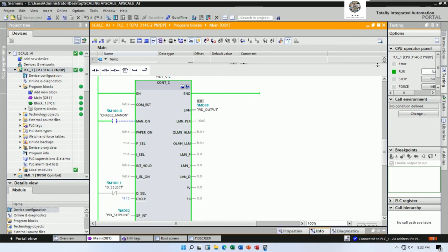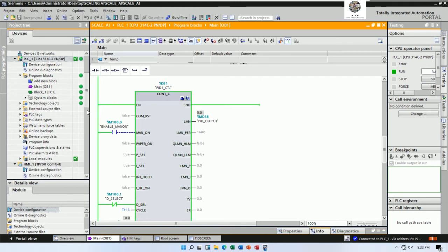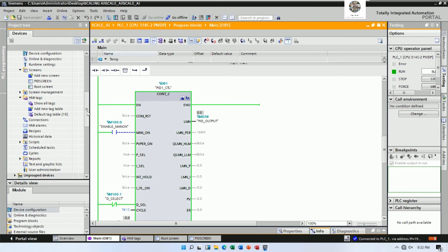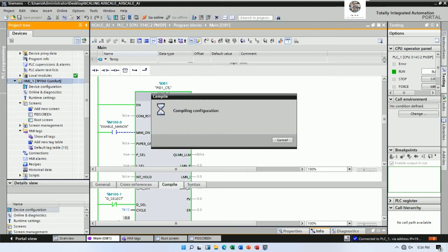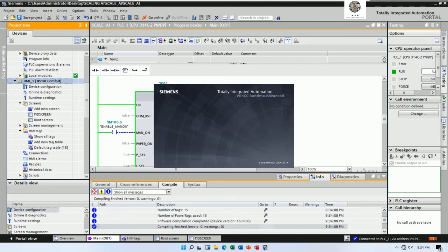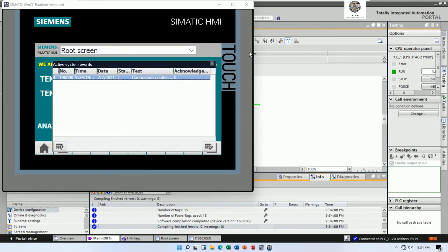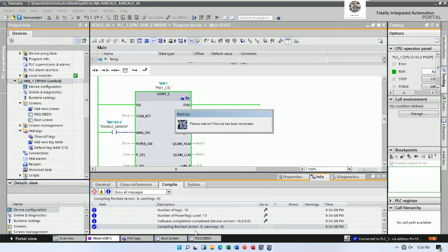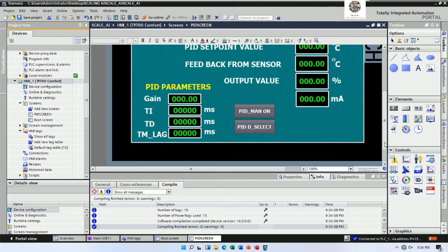And then we can minimize some feature. So let me go to HMI and then simulation. Oh, we need to call the screen PID, right? Otherwise we cannot see because the load screen is the default screen here. So I can go to the screen to call the screen.